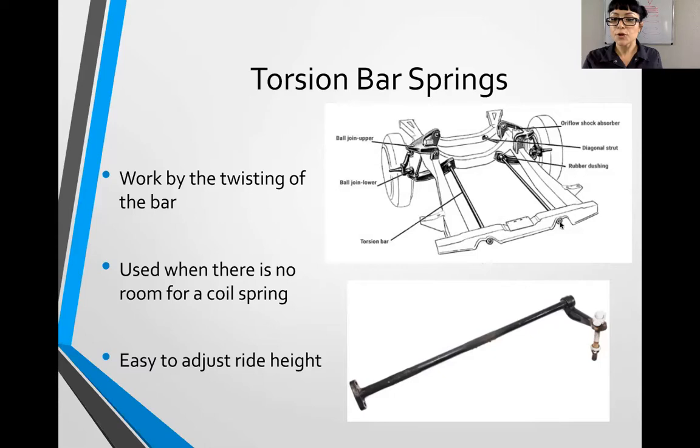So they're gonna have some sort of cross member back here that is attached to the frame or unibody, but the frame nonetheless. Over here, and this is how they work in the front, not the rear, but the same principle. Here we've got something called a control arm. I know we haven't talked about this yet, but as the tire moves up and down, this control arm is going to move up and down and pivot on the frame. Well, since my control arm is moving up and down, let's say it's fixed to the frame here through a bushing, and it pivots like this as the wheel moves up and down.